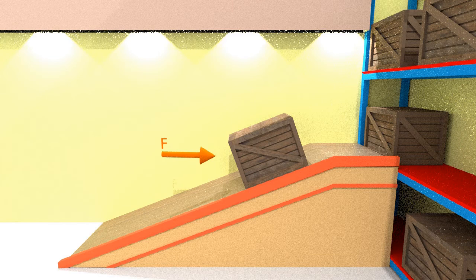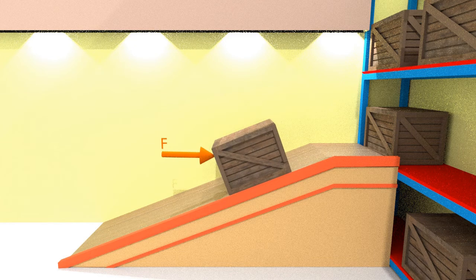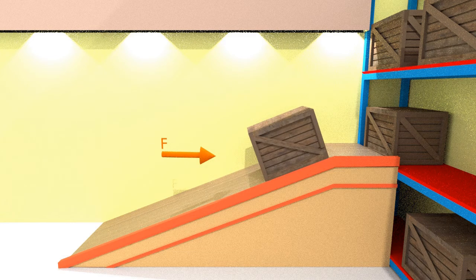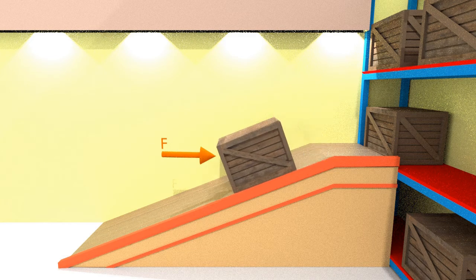Now this small statement has changed the whole scenario. We want to hold the box in position, which means that a force of such an accurate amount should be applied so that it will not only stop the downward motion but also will not make the box move in the upward direction. The box is neither moving in the horizontal direction nor in the vertical direction, so this is a problem of equilibrium where the resultant force of all the forces acting is equal to 0.